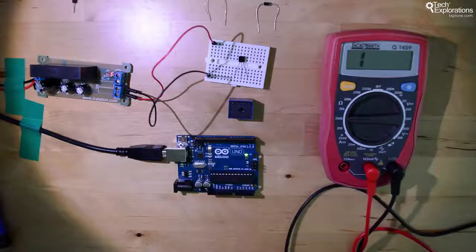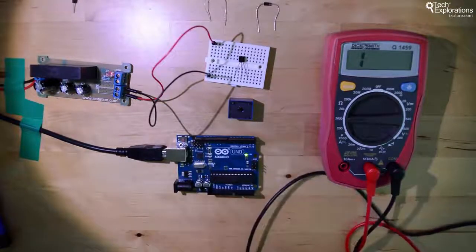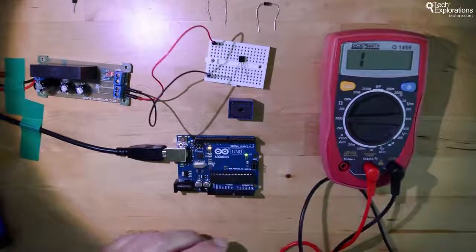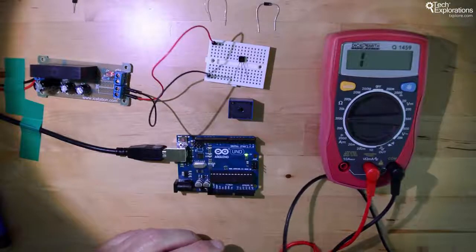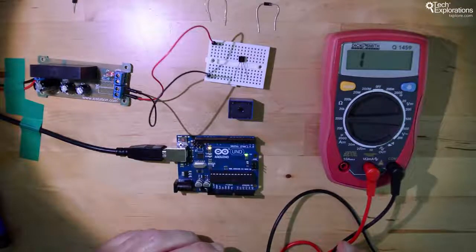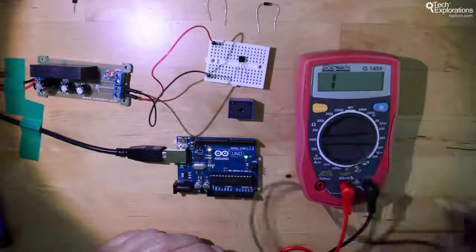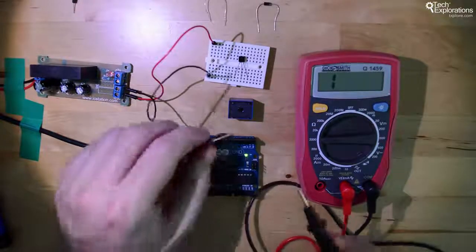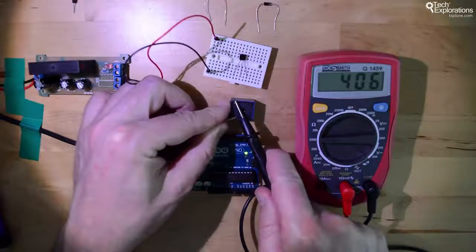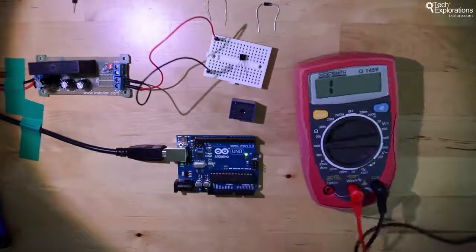The first thing we need to do is calculate how much current we need in order to energize the coil. Just like in the first demo, to figure that out we first measure the resistance of the coil, and from that use Ohm's law to calculate the amount of current that needs to flow through it. So I've got my multimeter set for resistance measurement. Let's check how much resistance we have in the coil. There's 406. Okay, 405, say.